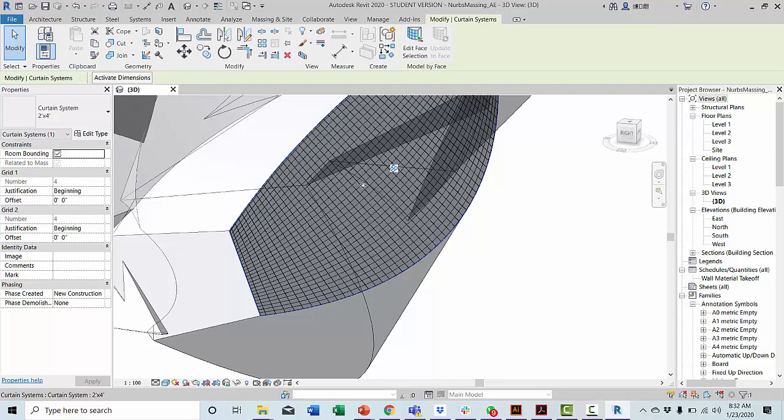But if you're gonna use a grid system with different louvers and elements, you may want to select all the louvers. So whenever you put the sun, you will see how that face of that mass is being affected by all these elements that are protecting or reducing the amount of heat that it's gonna get. So when you run this analysis, you wouldn't select the windows? I wouldn't select the windows. Does that make sense, guys? Actually, I don't even think that it lets you select the windows.